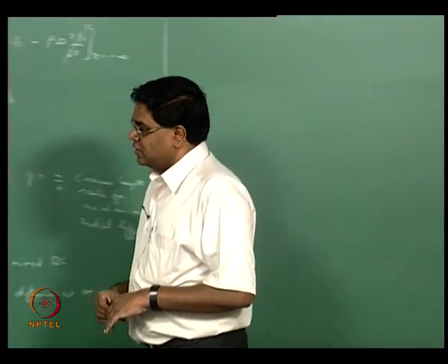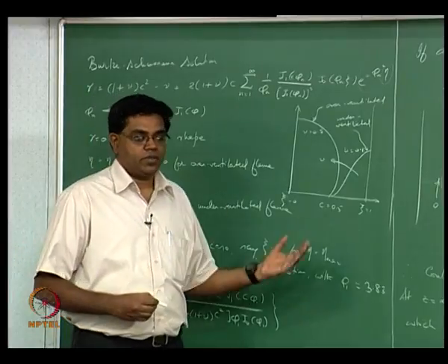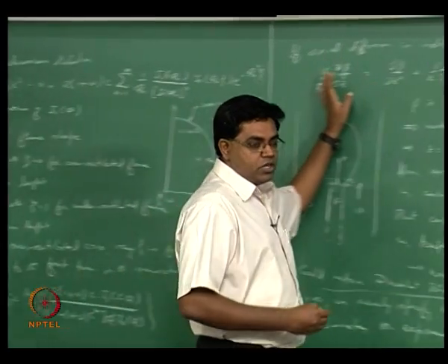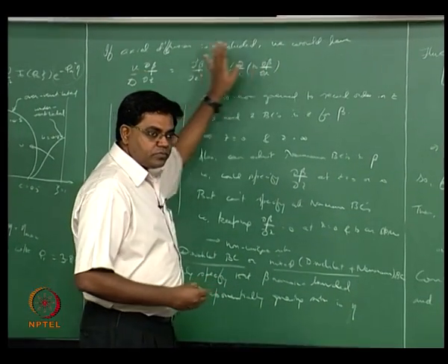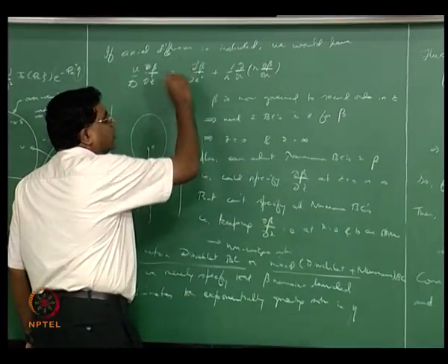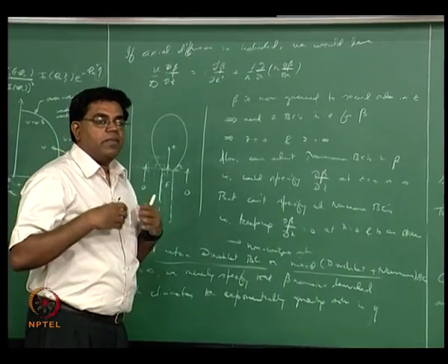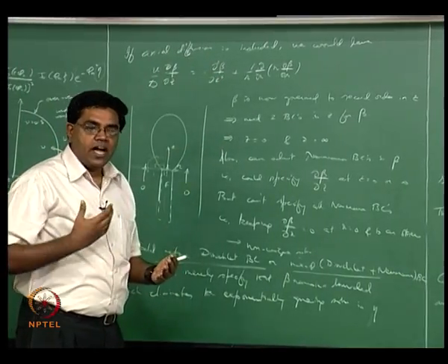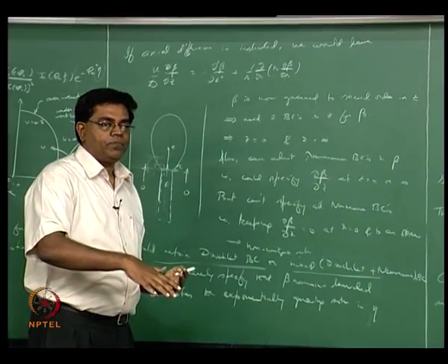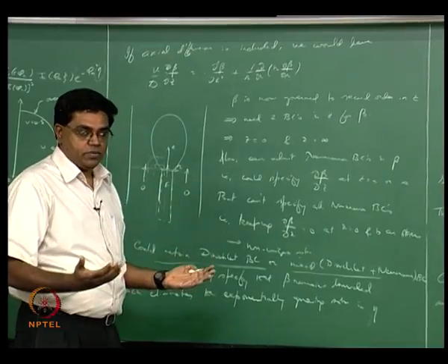The answer is, that now begins to depend on a new parameter which is called Peclet number. Before we didn't have Peclet number, we had a non-dimensional governing equation without any parameters. But now what will happen is you will have a 1 over Peclet squared showing up, and clearly what that means is, as Peclet number is large, the axial diffusion effect relative to axial convection is going to be small. Okay, that means axial diffusion is important mainly for small Peclet numbers, right?